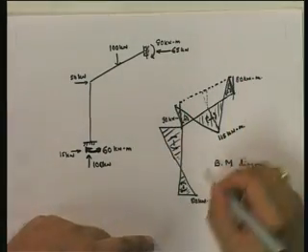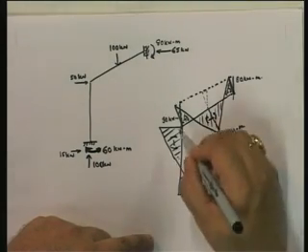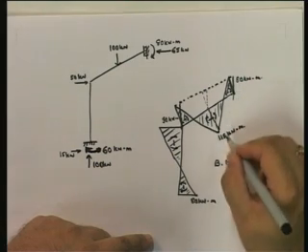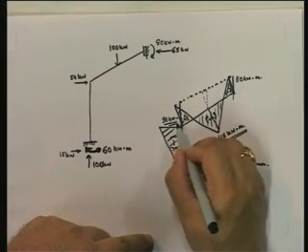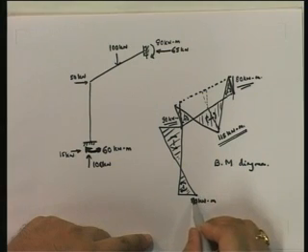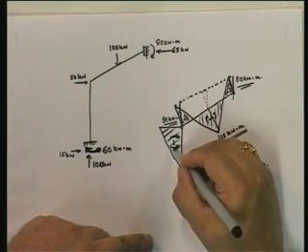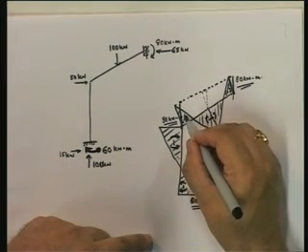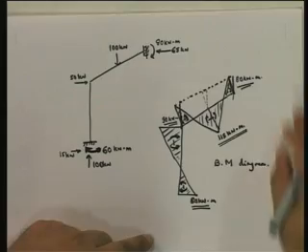Once you know those, you can always draw the bending moment diagram, and this is how it looks. Linear here, continuous here, this is superposed on top of this, and so this over here at the center of the beam is 115 kilonewton meter. At the ends of the beams it's 90 and 80 here, and 90 and 60 here. This is the sense of the bending moment. This is tension on the top. On the left hand side, tension is on this side, here tension is at the top, here the tension is at the bottom, here again the tension is at the top. I hope this is exactly what you have got from your solution.